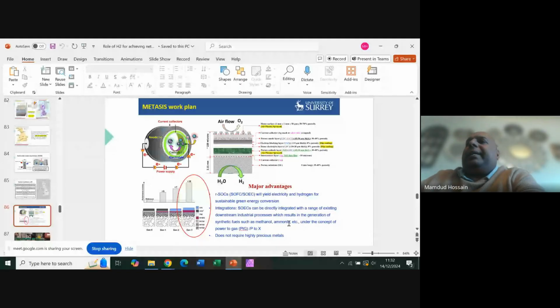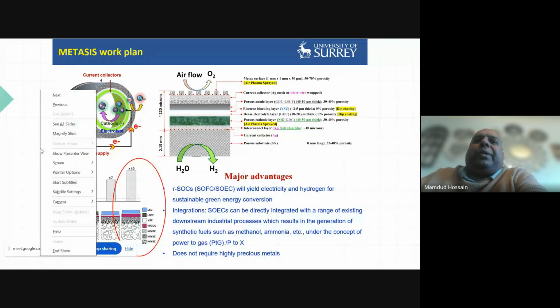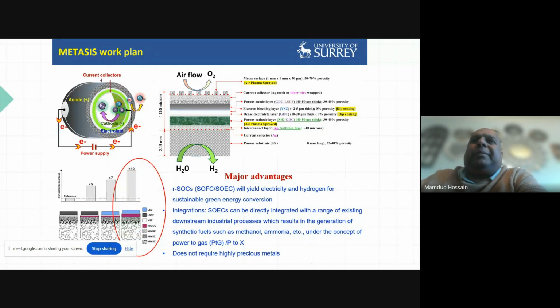What we have in solid oxide electrolyzer, I will explain the science a little bit now. So if you look at this figure here on the left, what you have is a tubular structure. In this tubular structure, we usually have three layers. One is this green part, which is what we call cathode. Then there is a white part, which is electrolyte, and then black and white part here is called anode. So three layers: cathode, electrolyte, anode. And this is then connected with an outer power supply. We take electron from anode and supply the electron into cathode.